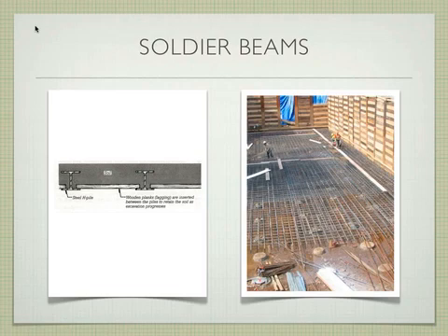These are the beams. They go into the ground, and they'll come back up through the surface of the earth too. So this way you can brace your wall to it. You can attach bracing to these. We'll get to that. A cold joint is when you pour that first and come back later and pour that wall second. You could do that, or they're going to do it at the same time. They're going to ram the piles, and then they have to excavate before they can add that wood planking. And as they excavate, if they need bracing, then they'll put the bracing in.